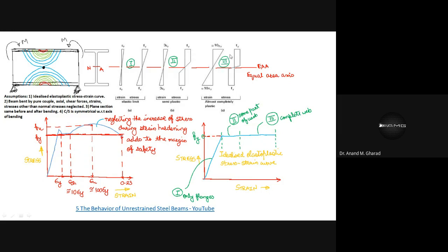And within the stage number 3, that is from here to here, again it is completely straight. And because of which the variation of the stress over here in the stage number 3, wherein complete moment has been used and complete stresses are developed, at that location you will find the variation of the stress to be again a straight line.